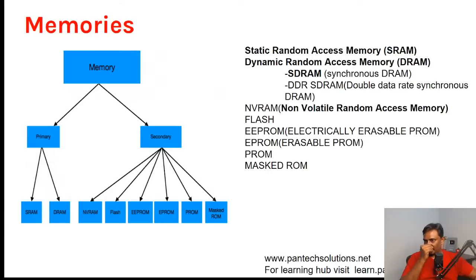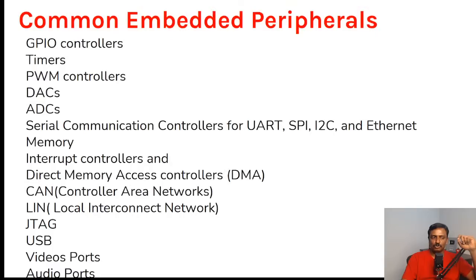If code exceeds the flash, what happens? Rohit Roshan, this answer is for you. This is where the linker script comes in. It will give you an error. You will not generate the hex file if the code exceeds the memory. That's where the linker comes into play.